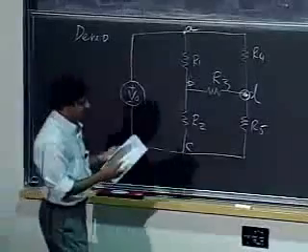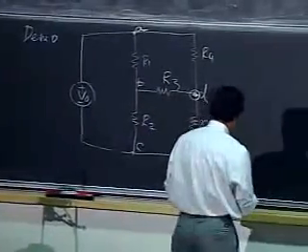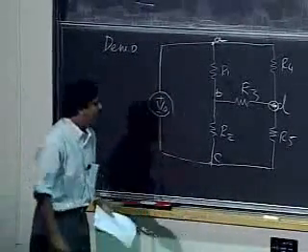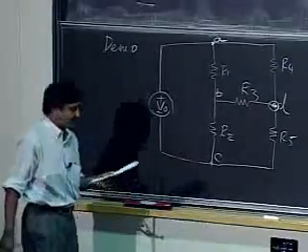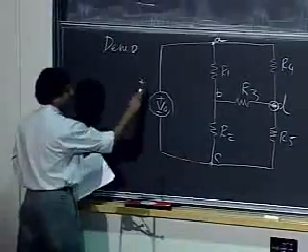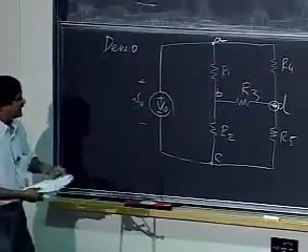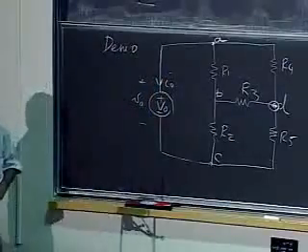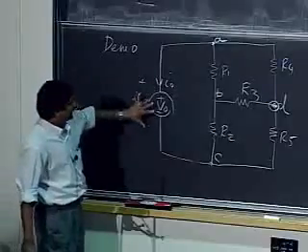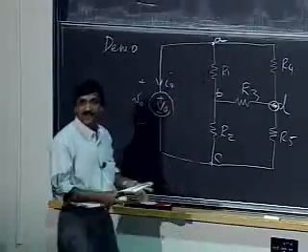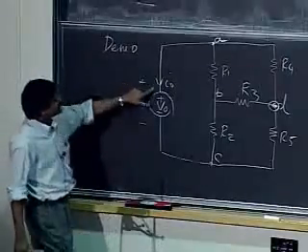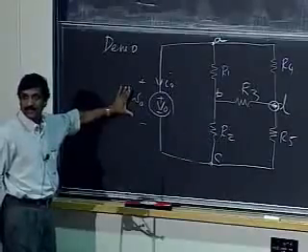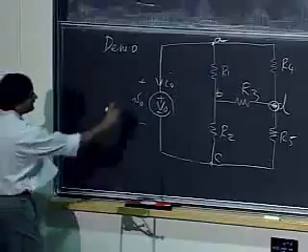Okay, so as the first step of my KVL KCL method, I need to write down all my element VI relationships. So before I do that, let me go ahead and label all the voltages and currents that are unknowns in the circuit. So let me label the voltages and currents associated with the voltage source, I0. Notice I continue to follow this convention where whenever I label voltages and currents for an element, I will show the current going into the positive terminal of the element variable voltage. So here I have V naught and I naught.